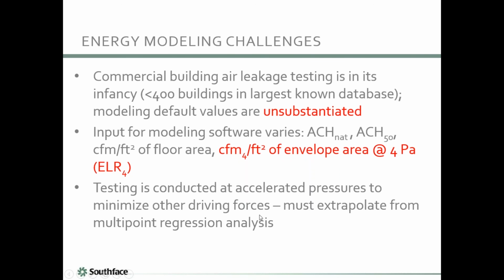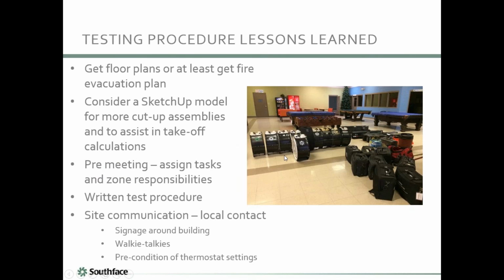Get floor plans, or at least get a plan, so a map to work off of. SketchUp was nice, mainly SketchUp. You're going to need to calculate the shell area of the building, and SketchUp was really useful for that if it's a complicated shape. If it's a cut-up shape, absolutely. If it's a rectangle, you can do it by hand.